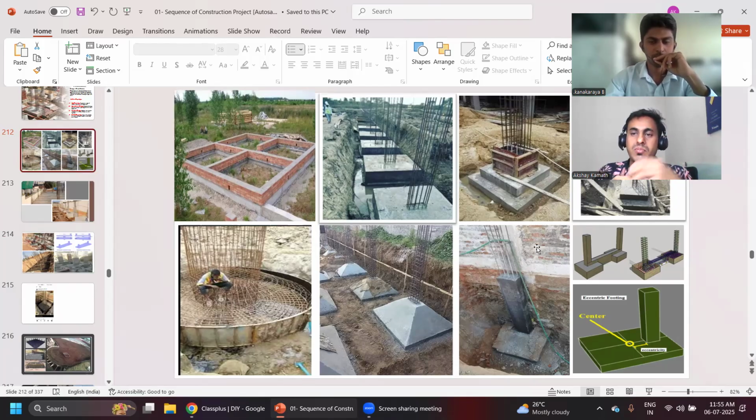So in the neighboring plot, in order to bring it inside, one option is that it becomes an eccentric footing, but you always have to connect that with the beam. Or you can design it as a pedestal to avoid the punching shear.